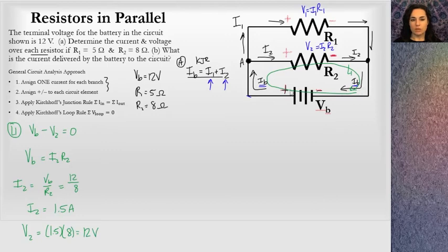This makes sense to me because when I do this loop, there's only 2 circuit elements. So this resistor is getting all of the voltage from the battery, is how I think about it. Let's choose a different loop. I still don't know I battery, so let's choose a different loop to find I1. Let's do something you might not expect. You might want to do a loop around the outer, but what I'm going to do is choose a loop around the top here.